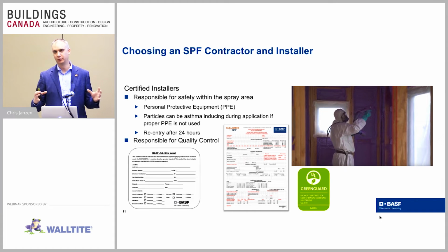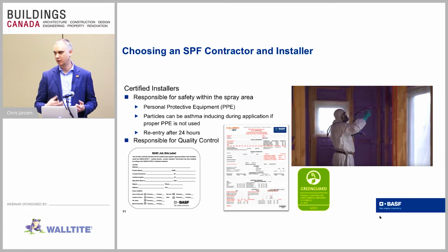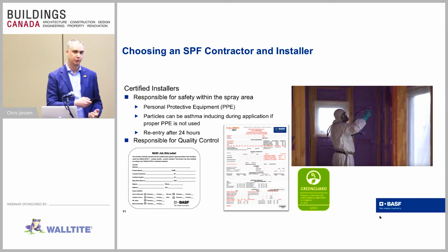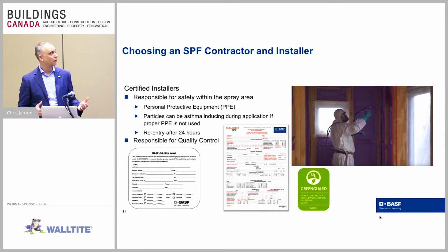The particles that are produced from the spray foam application can be asthma inducing, basically cause occupational asthma if you're not wearing the proper PPE. And that's why the installers are trained to make sure everyone's out of the spray area. So they should have signs up, warning tape posted, warning signs, and isolate the area from other trades that might be on site and have ventilation provided for that. And with all that stuff, that's basically just making sure that the site's properly controlled and everyone's safe on there.